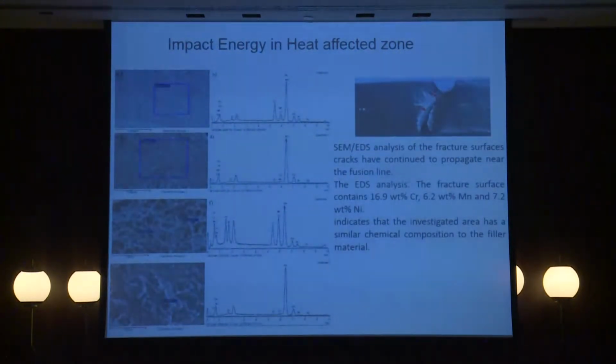After that, I want to point out that all cracks follow the fusion line, as you can see, at all investigated temperatures: 20, 0, minus 20, and minus 40 degrees.